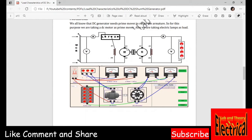From the generator side, A1 and Z1 are short circuited at this point and connected to the ammeter. Then the ammeter negative terminal is connected to the voltmeter, and this total portion is connected to L1.